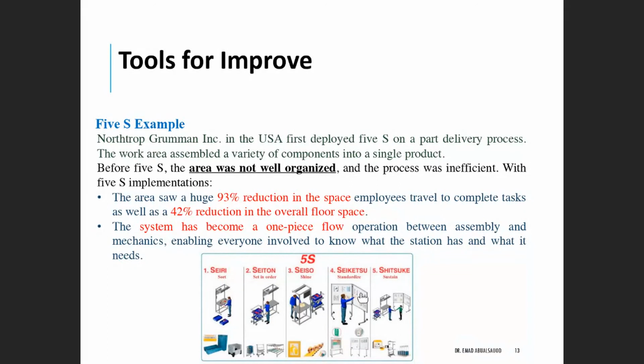And standardize the process. Instructions can also be written, so anyone working in that area knows how to follow the 5S concept that you implemented: returning the equipment to the right place, how to use the equipment, how to leave the place as clean as you received it, and so on. And sustain, and always make continuous improvement and checking actions along the way. This was for the 5S.